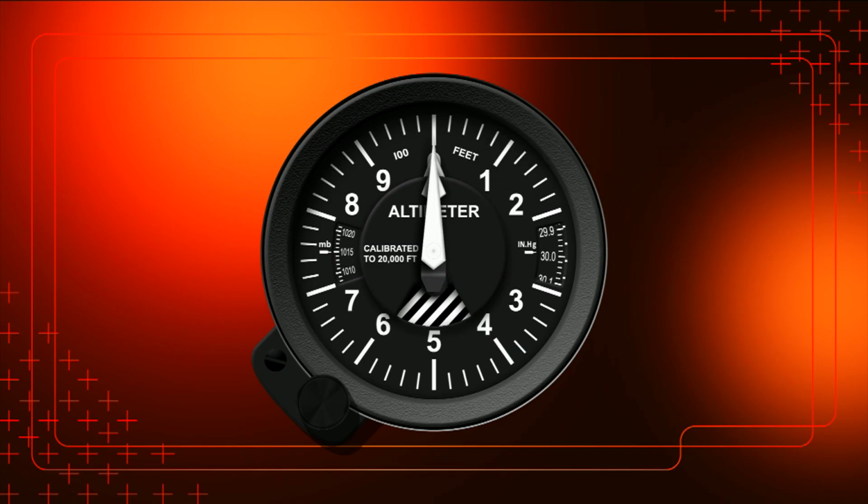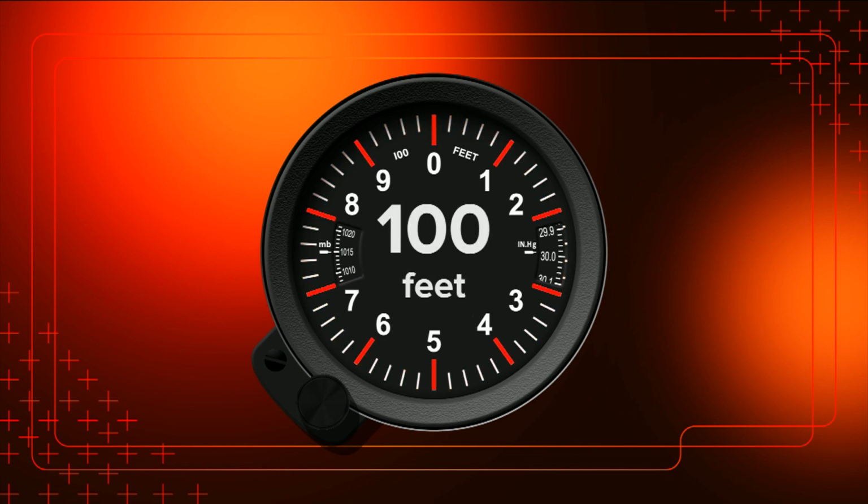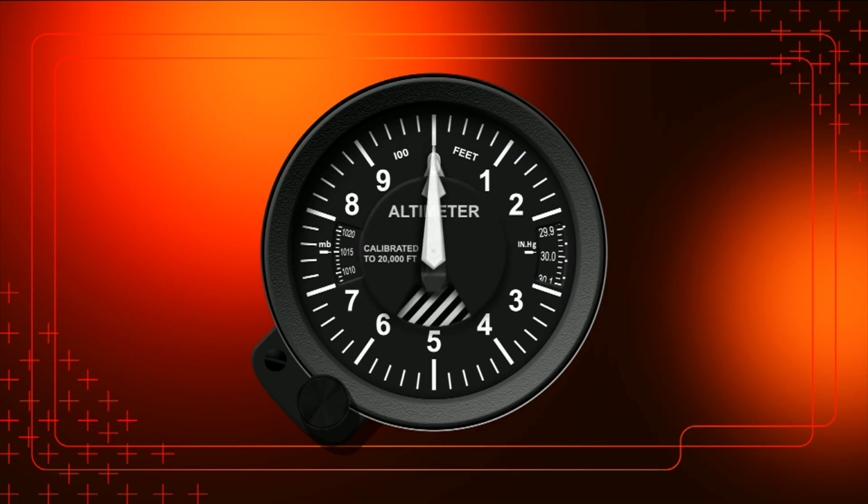in feet. Moving on to the various height scales on the instrument, the small white lines around the circumference of the instrument represent increments of 20 feet, and the larger lines indicate increments of 100 feet. Being able to correctly represent what altitude is visually represented on this instrument is crucial to a pilot. So, we are going to briefly walk you through how to read specific altitudes on this analog altimeter instrument.